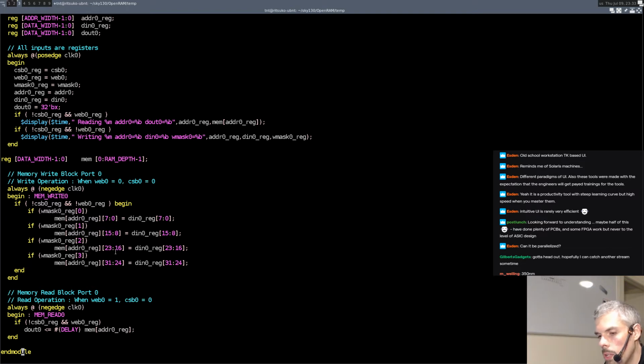So the whole logic they implement uses the high period of the clock, from the rising edge to the falling edge, to pre-charge all the SRAM bit lines, and then does the actual read or write at the falling edge of the clock, which means you basically lose half your clock cycle without even considering the clock to out of actually reading the SRAM, right?